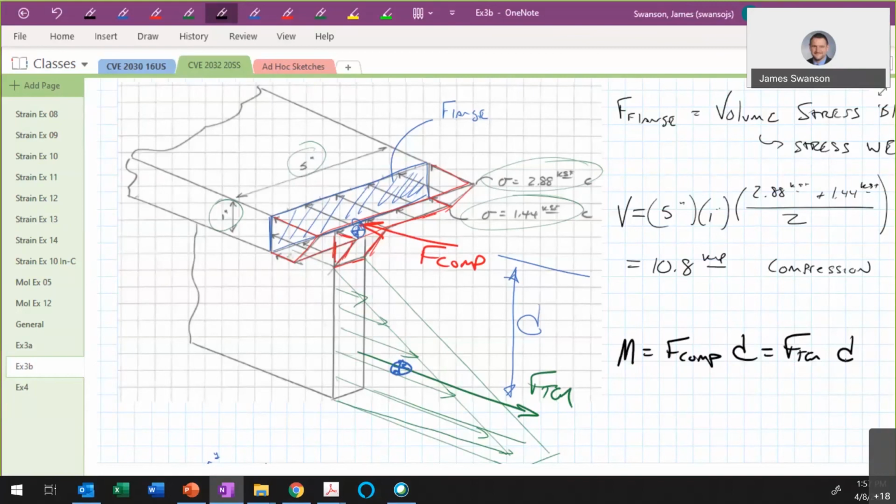The stress that results is perpendicular to the plane. So if we have a moment in the z direction and y is vertically upward, then the stress is in the x direction. If you have a moment about the x-axis and y is vertically upwards, then you have a stress sigma z instead. And then you can calculate the stress. The distribution of stress over the depth of the part is linear.